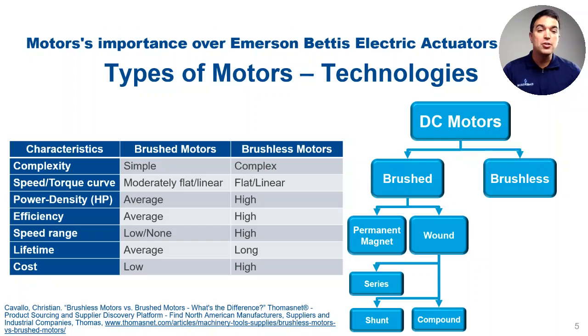Now, brushless motors. They take the permanent magnetic field usually housed inside the brush motor stator and place it around the rotor in the form of actual magnets. This technology has long life, low maintenance and high efficiency, but higher initial costs and more complicated controllers.